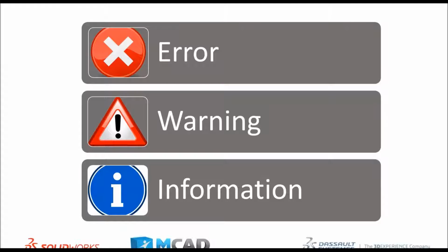The second one is going to be warning. These indicate that there might be a possible error with the data being absent. It's possible that there is a wire without gauge information, or a connection of the wrong type, or it is also going to notify you if there is no valid path for the routing to latch onto.